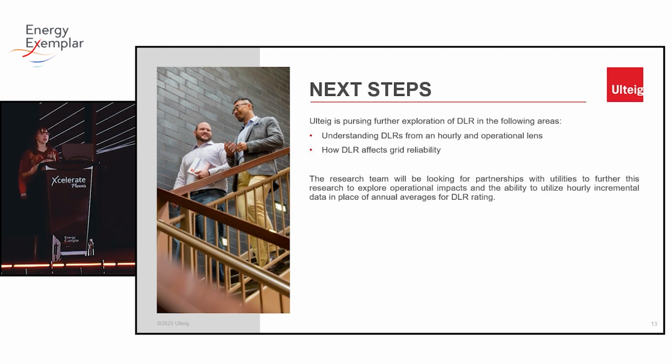How does Ulteig see this type of research continuing, or what do we want to look into next? So something that is an option for continuing this research would be looking at how DLRs operate from an hourly perspective. This would require using hourly or even sub-hourly data, which was not available at the time of this analysis. So what we did in the presentation and the results that we just showed you was we used an annual static dynamic line rating value based on input from Line Vision. And we did that in order to just create a bounding case and to test the annual version of this.